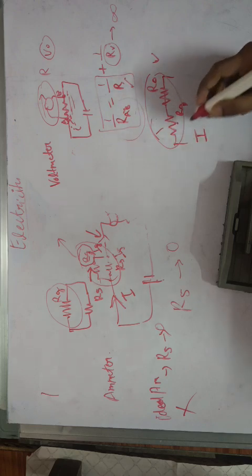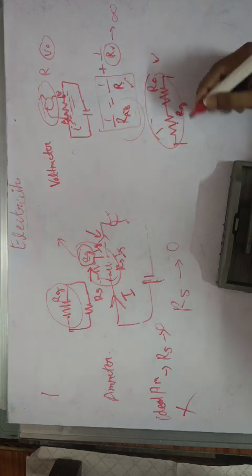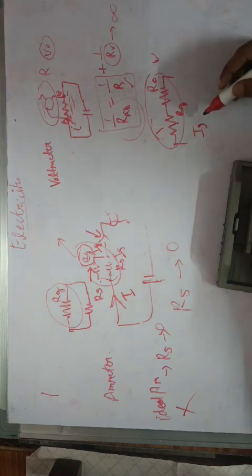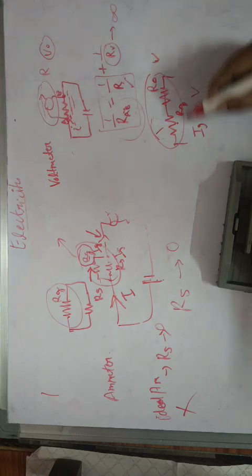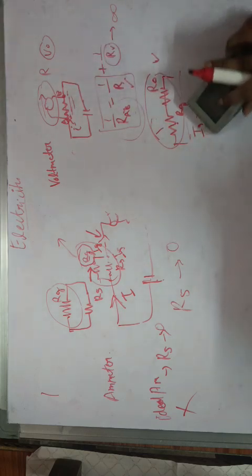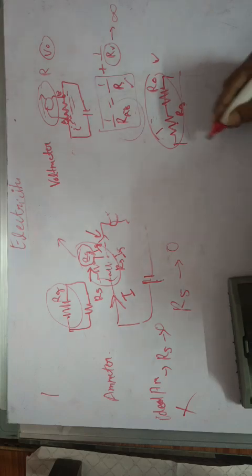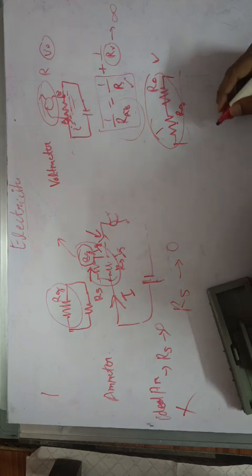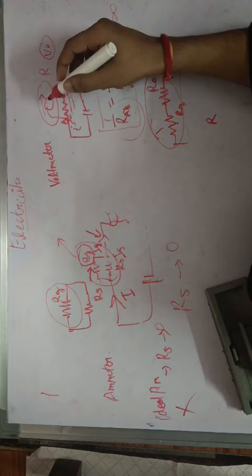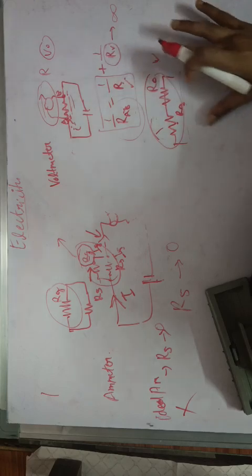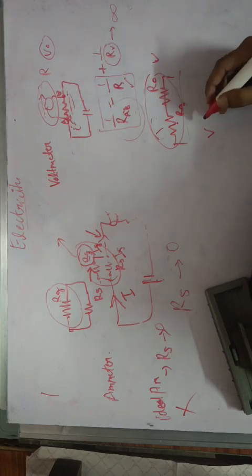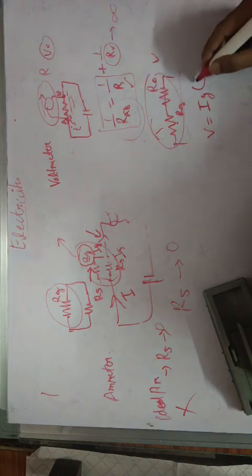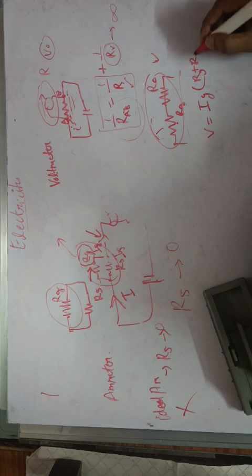And we know that the current flowing through this galvanometer, which is Ig, has some relation to the potential across this whole circuit. How it is related, we can say that the total resistance across AB is, let's say, R, and the total potential difference is V. And since current Ig is flowing, Ig would be equal to V over Rg plus R naught.